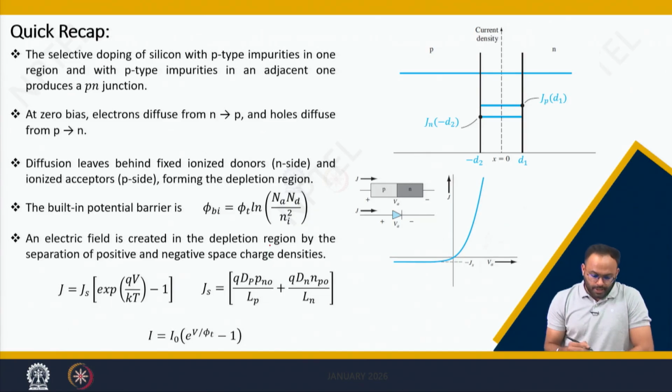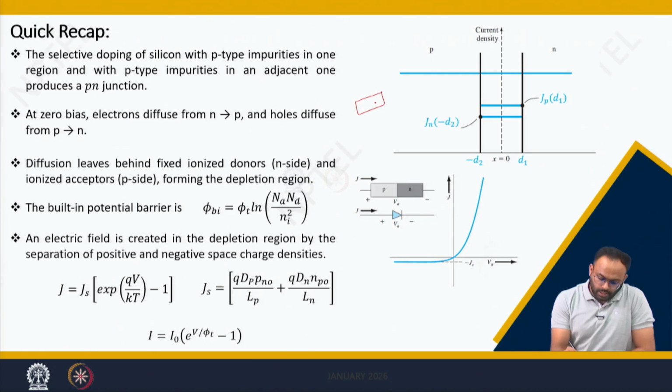In the last lecture, we discussed that when P-type material is combined with N-type material, they form a junction at the metallurgical junction, and because of that, a huge amount of holes will go from left to right. Similarly, the electrons will go from right to left. This causes a diffusion current in the PN junction, but this diffusion current is counterbalanced by the drift component.